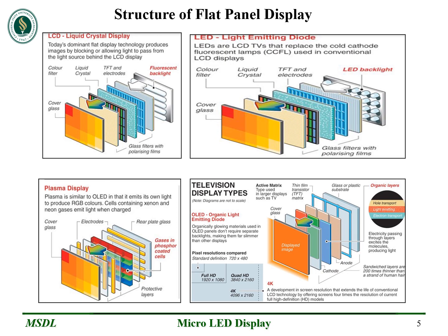Structure of flat panel display. LCD stands for liquid crystal display. It involves having a backlight, usually fluorescent, with an LCD screen in front of it. The LCD screen is where the images and the colors actually come from. One of the drawbacks of LCD is that it can never produce true black, because the screen would have to be completely opaque or solid in order to get true rich deep black. However, the advantage of LCDs is that they are relatively inexpensive these days and, unlike the traditional CRT tube, they are extremely thin.